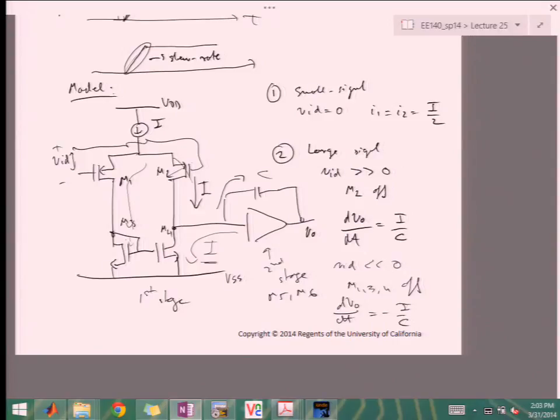So it's moving you in the right direction, but the shape in which you're approaching that target magnitude is really independent of the small signal dynamics, of the linear system dynamics. And so this quantity over here we call slew rate.